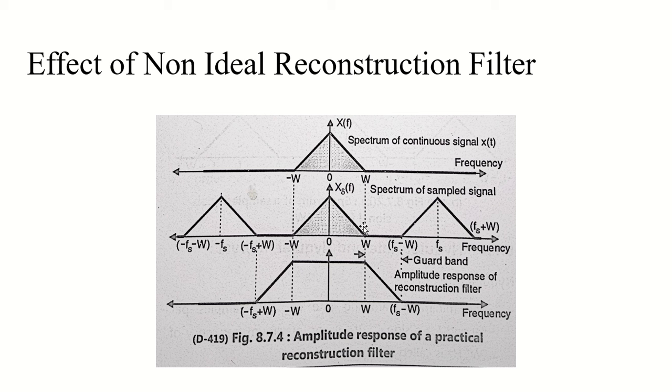A practical low pass filter with a frequency response as shown here, with fs plus omega and fs minus omega, can be used without introducing any distortion, due to the presence of guard bands between adjacent frequency spectrums.